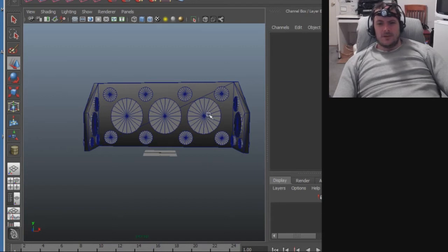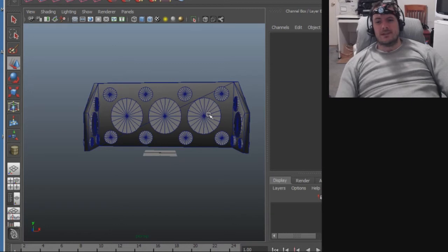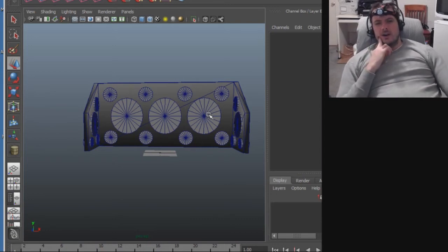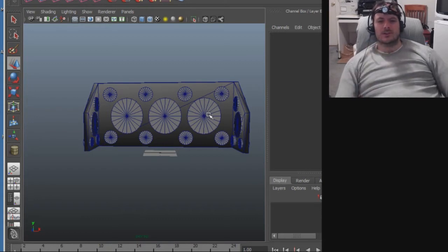So you have to fill in the holes, overlap the fill, sand it smooth, butterfly it in, just like filling in dents in a car, and then paint over it with a thin veneer of ABS juice in order to create a crystal clear, smooth finish. Not a clear finish, a crystal smooth finish that has no indicators that you ever printed with holes in it.